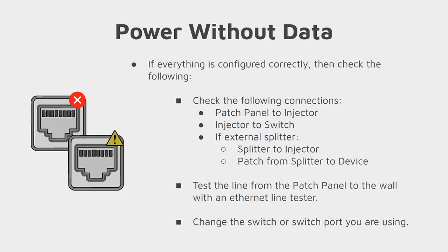Another thing, you can change the switch or the switch port you're using. If you are using a POE switch, identify another port that provides POE or turn on POE for that port and test on that port. Just another real quick thing to rule out.